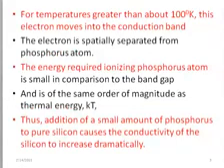And whenever you increase the temperature from absolute 0, that is minus 273 degrees Celsius, if you raise the temperature to around 100 Kelvin, it will give enough energy to this electron, that is the 5th electron which is not bonded to any of the atoms. It will give it enough energy to now start moving from where it is into the conduction band, and this electron will now become physically separated from the phosphorus atom, and for this reason it is mobile.